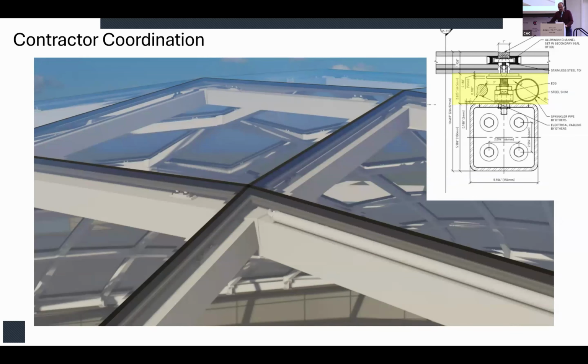There's nothing worse than having a drain pipe that's bigger than your structure, right? So for this particular type of grid shell structure, you don't want a big gap between the glazing and the steel. It'll make things look twice as deep. We did need a gap for detailing, right? With this particular subcontractor, that's how they wanted to do it. And we tried to use that gap to stuff this sprinkler pipe and conduit into it.